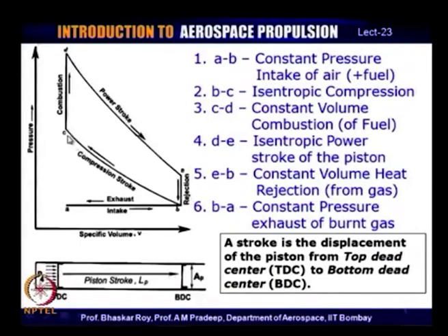and the process of compression occurs along that. And then process from C to D. Now, this is combustion. This occurs under a constant volume process, during which, as you can see in the PV diagram, there is no change of volume envisaged in the ideal cycle, and as a result the combustion is expected to occur as a constant volume combustion process.